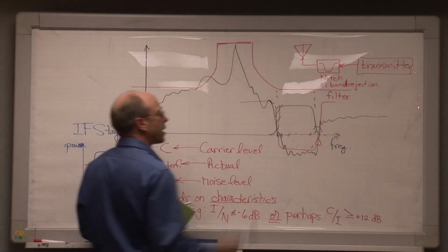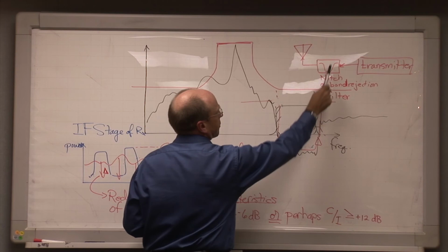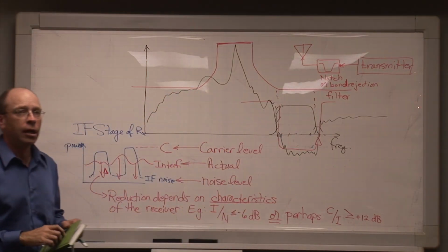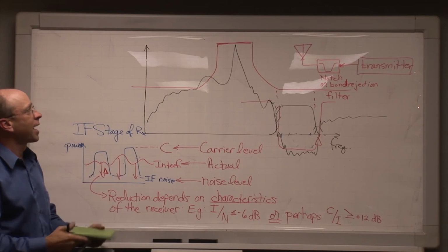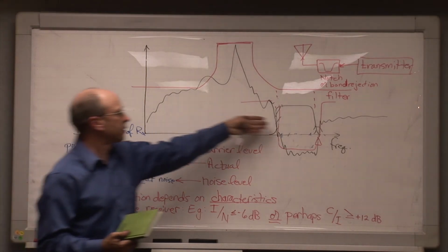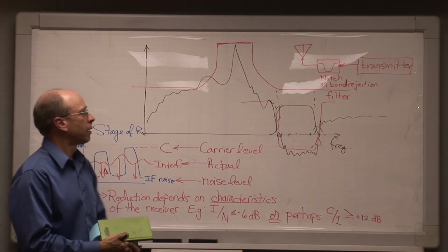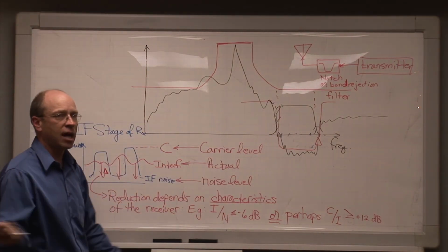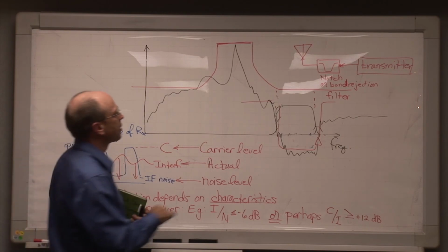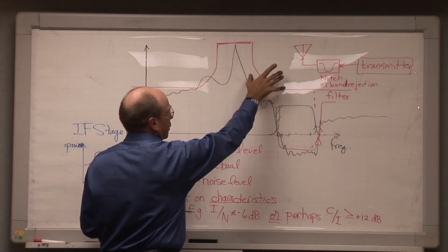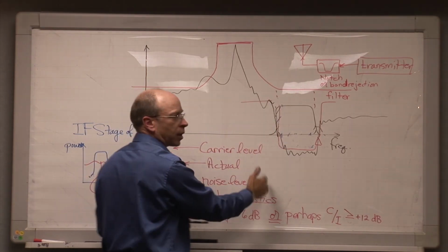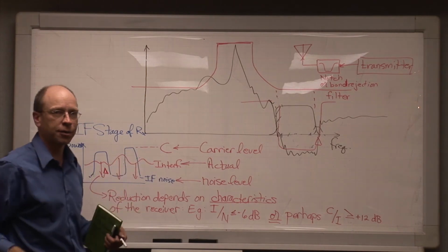So that we know how much this needs to be reduced, and we can then call a manufacturer on the phone and say, hey, we need a filter that works across this frequency range that has this many dB of rejection. Then we install it and we go to work. And we've had this happen any number of times with radar systems where the radars had spectra that looked like this. We've had it with other systems. It can happen, as Ariel commented, in a land mobile radio system where we have adjacent channel interference. In that case, the problem is to make the roll-off characteristic of the emissions from a transmitter channel even sharper than they were when the interference was occurring.